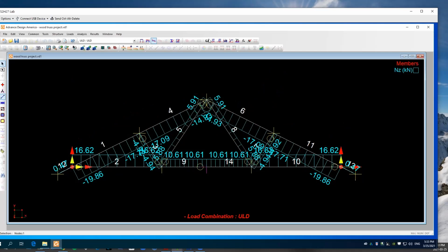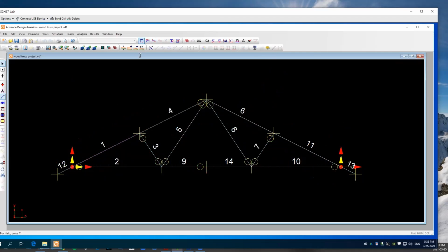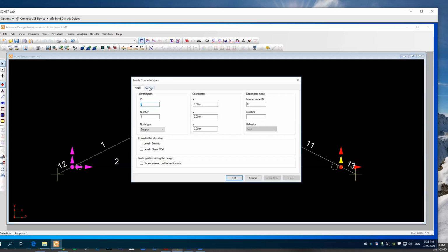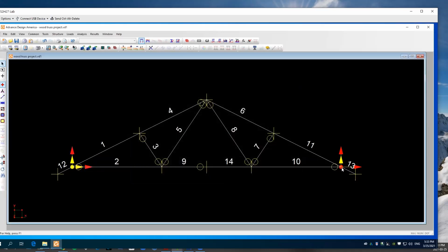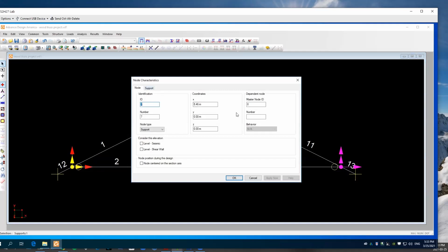Sir? Yes, go ahead. I have a question because I have the same as Alex. When he checks his deflection, do we use the deflection in the strong axis or axial deflection? You're always checking the deflection in the strong axis. Because apparently when I checked it, it doesn't work. Like the one in ADA is much higher than L over 360. You sure? For almost all of them, for the top chord, bottom chord, and...